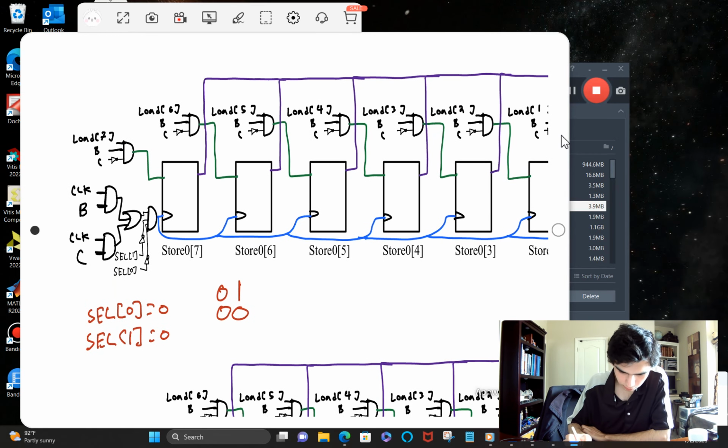Yeah, let's go back to the first one. So we state 0, 0, 0, 0, those two are 1s, so then the change is going to be dependent on this. So this will change depending on whatever that last input is. So right now both of these are 0 when nothing's pressed. The clock is always going up and down, but the output will always be 0 when B and C are 0, which will then keep this 0.